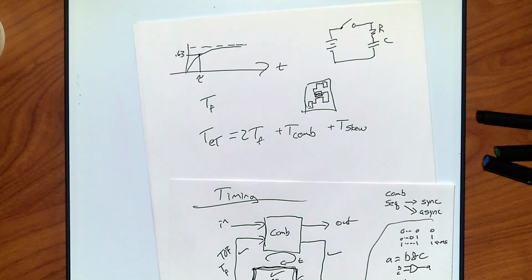Well, it takes time for your clock to propagate. Not every area of your chip sees it simultaneously. It's emitted from one location and it has to propagate. If you're closer to the clock, there's no skew. Skew is how much the clock has been shifted because it's further away. If you're really far away, it takes a little while before you see the clock, and the original clock has changed in that time. So the time it takes for the signal to get to you is called T-skew.